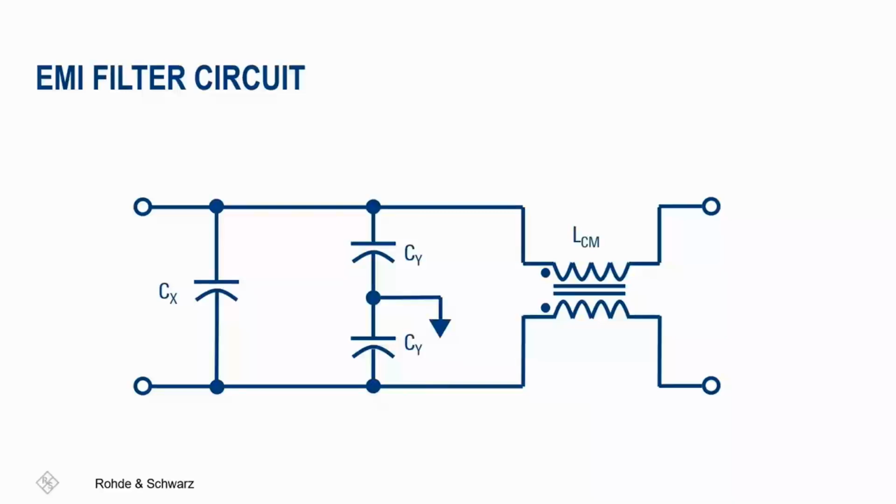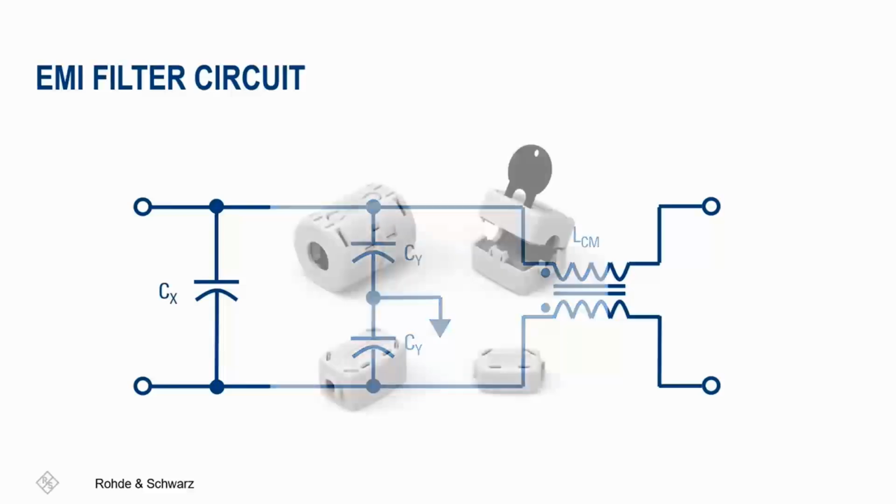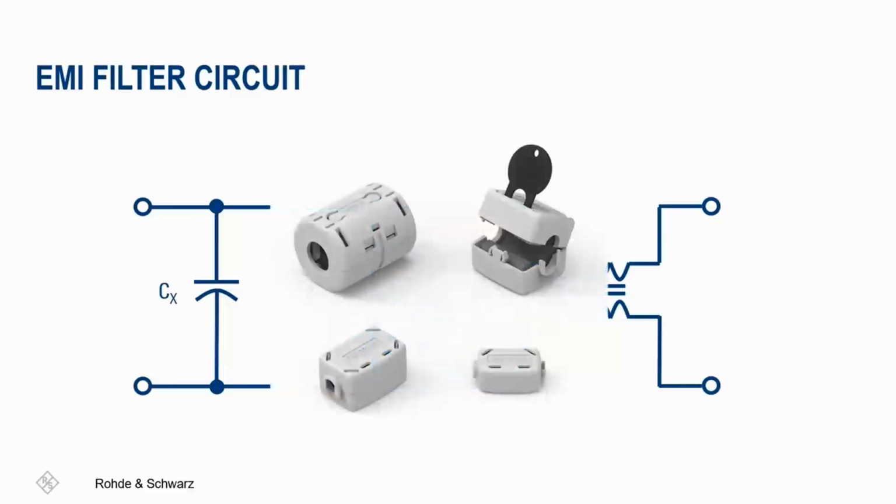Let's delve into understanding how an EMI filter circuit works. There are different approaches to handling conducted emissions. It can involve a circuit designed as part of the power input of the system. Alternatively, in cases where a product has failed in the EMC labs and didn't account for an EMI filter circuit, a quick fix can be achieved with ferrite clamps. While ferrite clamps offer a fast and effective solution, they may not be cost-effective if every inlet cable requires one.